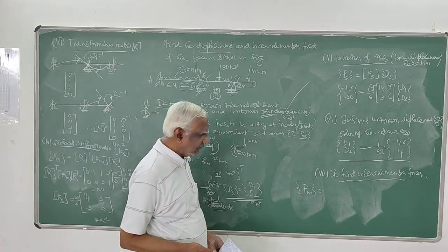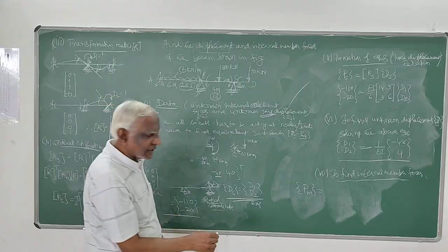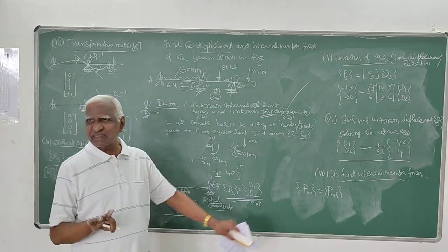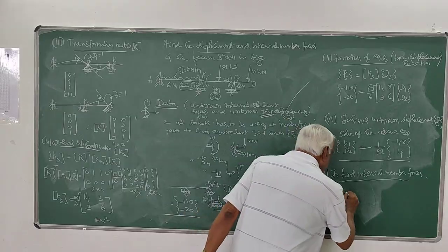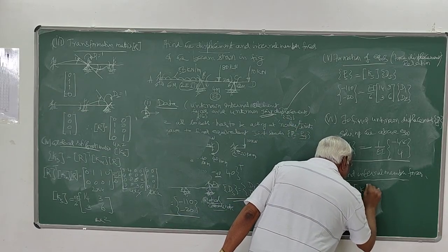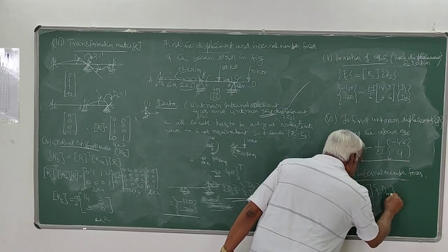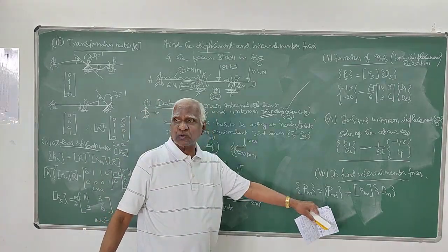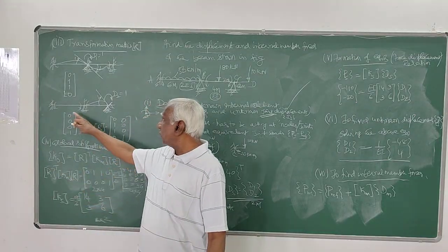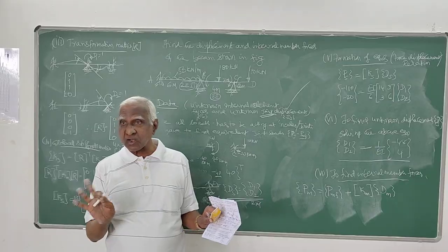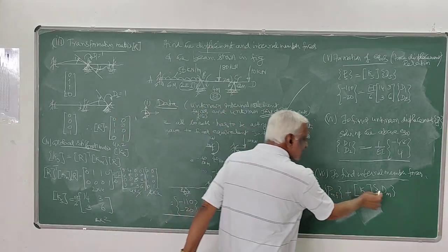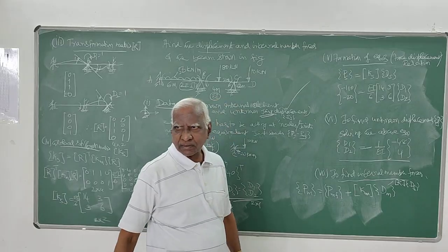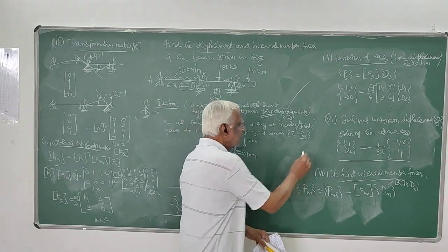So Pm is given here. There was a member load, that's why for that member load also we have to take the fixed end actions. Pms, this is the extra term coming. Pm is equal to Pmf plus Km into dm. So instead of just Km dm, I have to add Pmf also, that is the corresponding member fixed end action. That's all the change, nothing other than that. Of course, dm is nothing but R into ds.